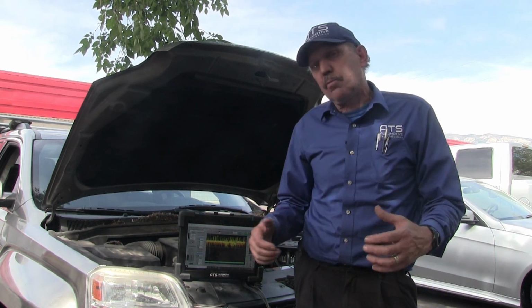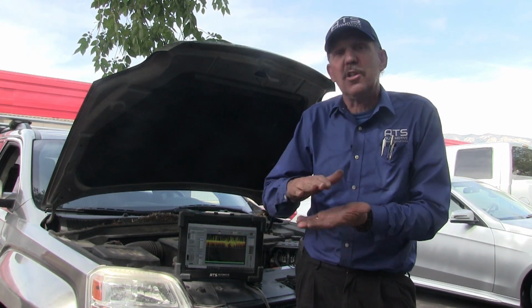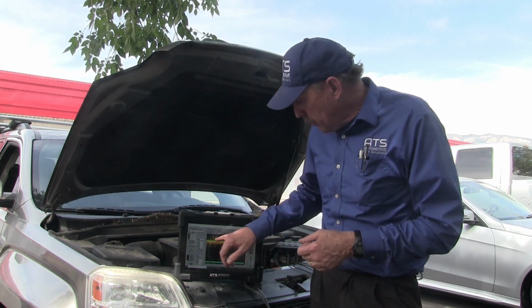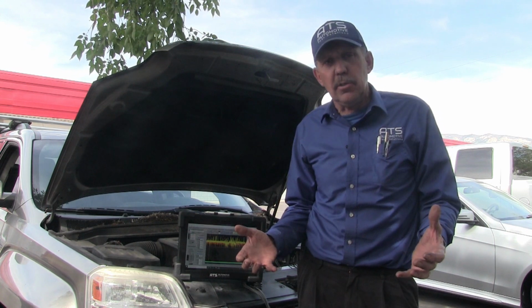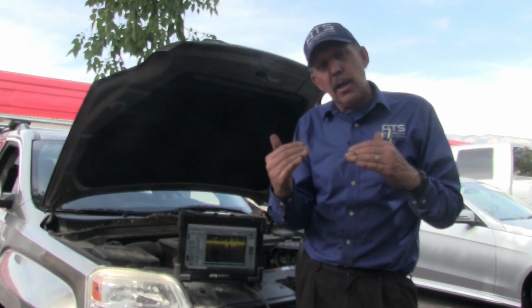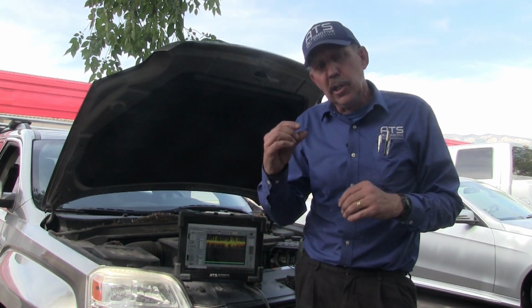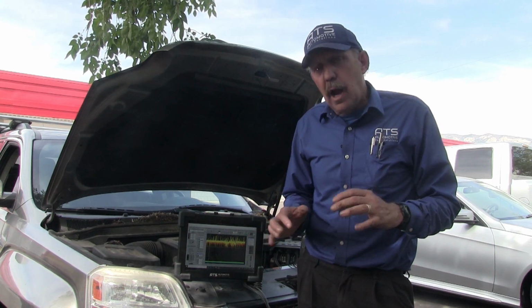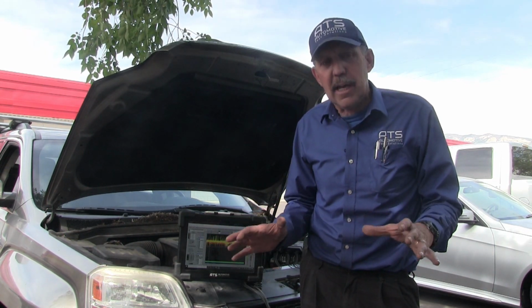But the bias really isn't producing voltage, the O2 is just riding on it. So we sort of have a problem with the O2 where it doesn't seem to produce, but what it's riding on is 0.3 of a volt low. So that's a problem. So what I want to do, I don't want to disconnect anything till we test it.